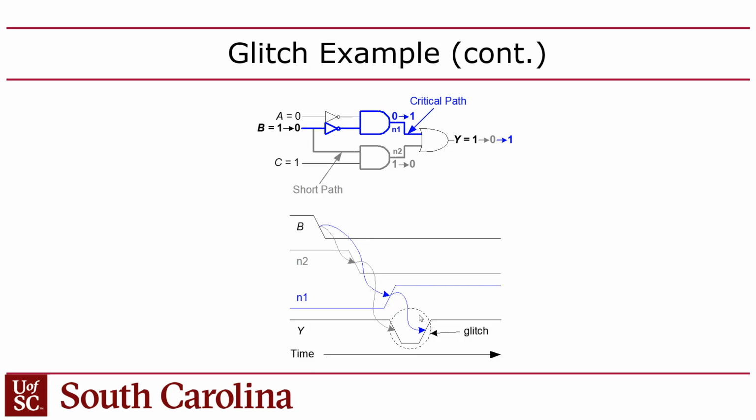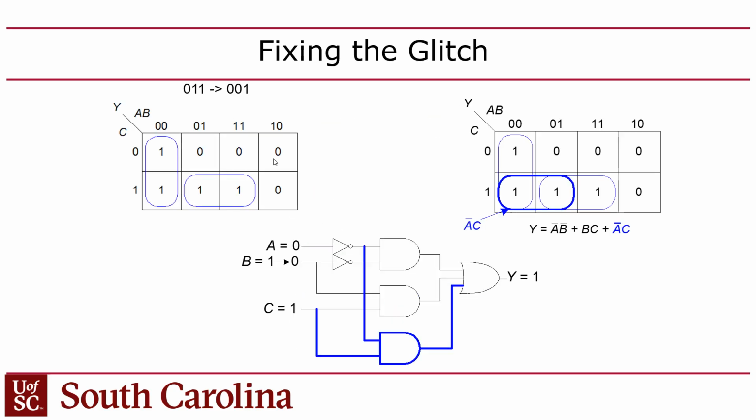And I don't know if any of you noticed this, but ModelSim, or QuestaSim, actually simulates glitches. Sometimes you'll be simulating your circuit and you'll see these weird little glitches. I don't know exactly how it determines that, because glitches are really a technology thing. In order to get a glitch, you have to map these to gates and find the paths through the gates, whereas ModelSim is just doing a functional simulation. Yet somehow sometimes you'll see glitches in there, right?